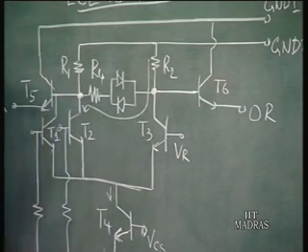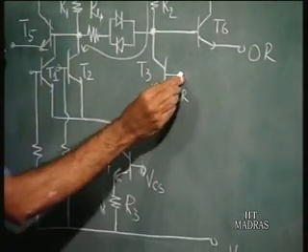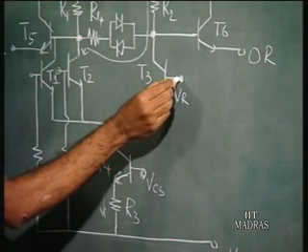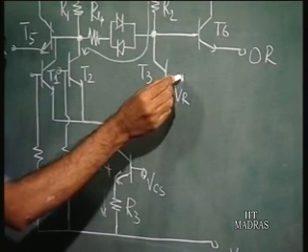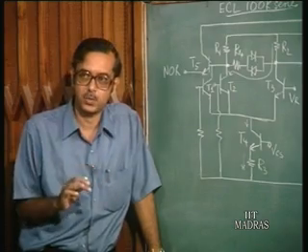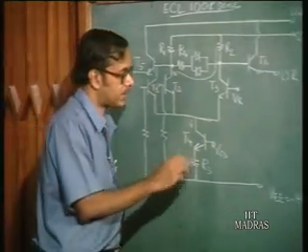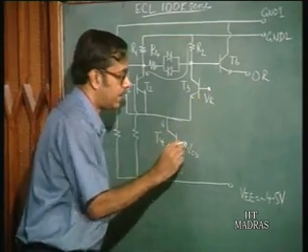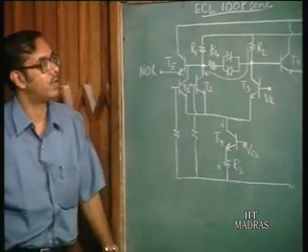So, we have an additional circuitry. Also, this I have not drawn, the voltage generation circuits for VR and VCS are properly temperature compensated, so that these voltages are fixed with respect to temperature. So, these are the modifications in the circuitry in this series.